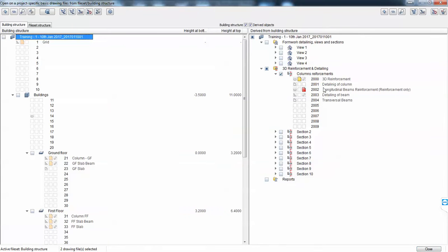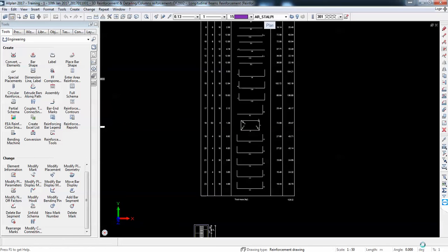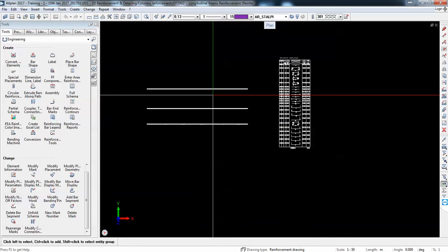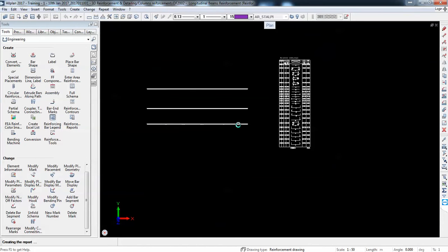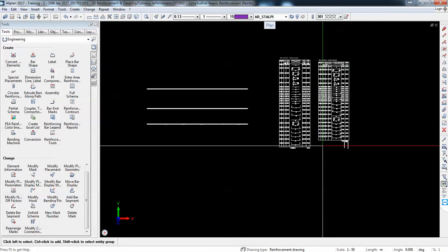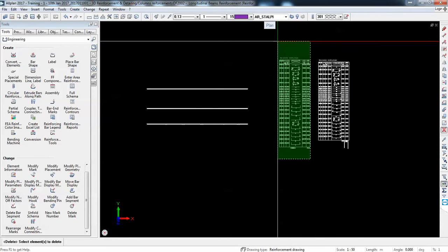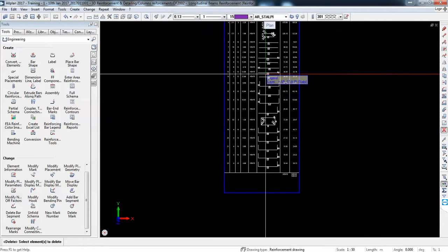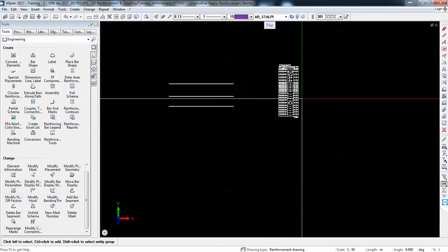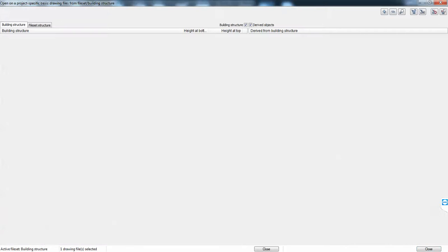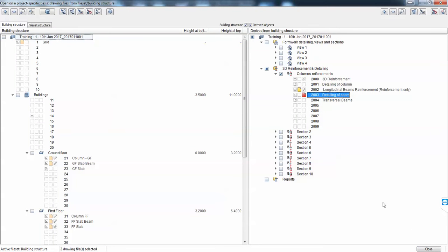So my recommendation also is, once you finish the detailing, because while detailing you might encounter different problems or solve different issues, always before plotting regenerate this list. So don't keep associative lists. Before plotting finally, do this list again so you make sure you get the latest version. Okay, now I will start detailing here.